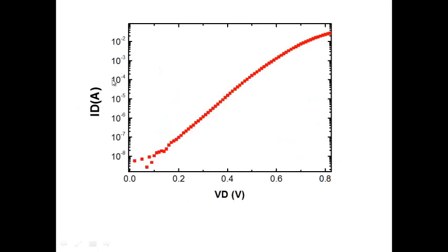And as I said, if you plot it on the exponential log scale, you can clearly see there's nothing unique about 0.6 or any other voltage here. The current is increasing as sharply at 0.6 as at any other place here. If you are interested in currents around 1 milliampere, if that's the range of current at which you are working, then you may approximate the diode by 0.6. If the range of current that you are interested in is, say, microamperes, you may approximate it by 0.3. So it all depends on what range of current is of interest to you.